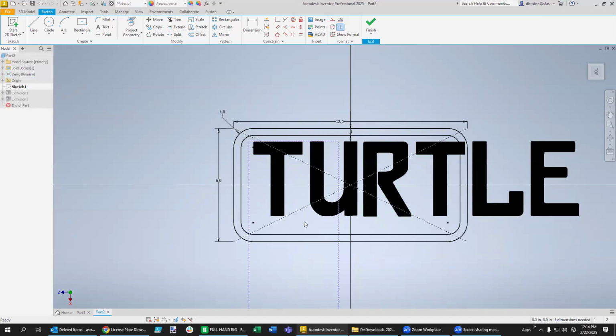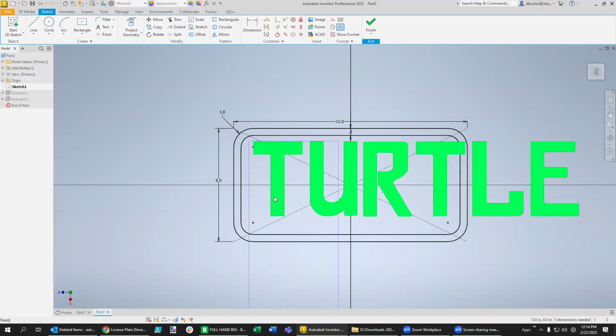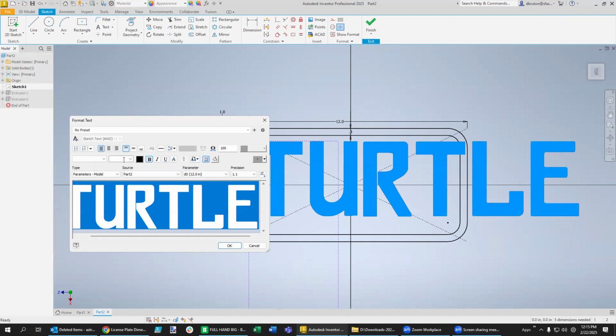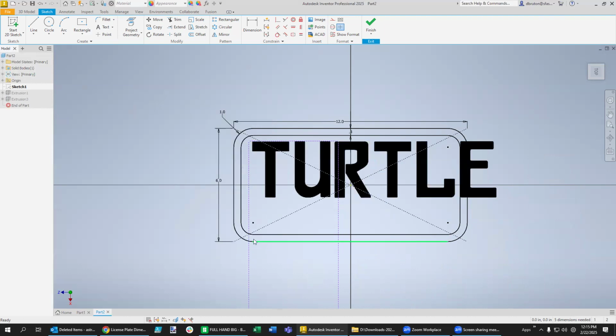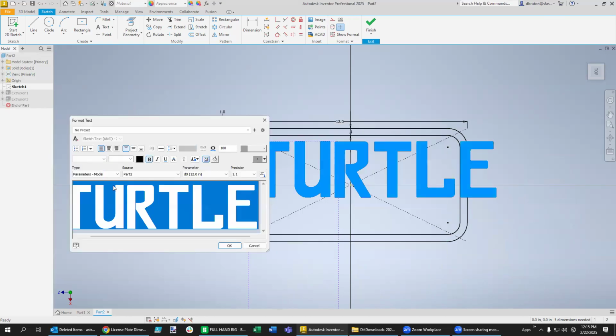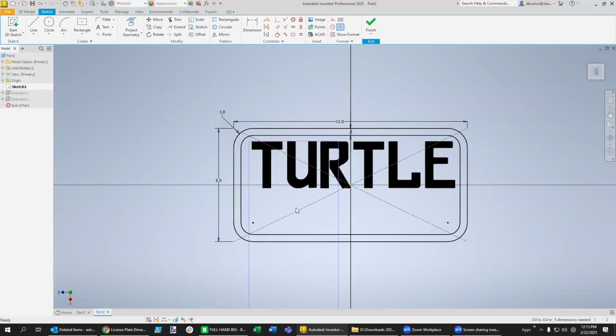And obviously my font size is too big. So let's shrink this down. Come to think about it, it seemed like you normally put the state above the number anyway. So that kind of makes sense. So let's reduce this to 3 and see if it's any better. So 3 inches, and that's getting closer. Let's do 2.5, and I think we might be golden. So make sure you hit Control A for the size of the font to make sure it's going to apply to all the characters.